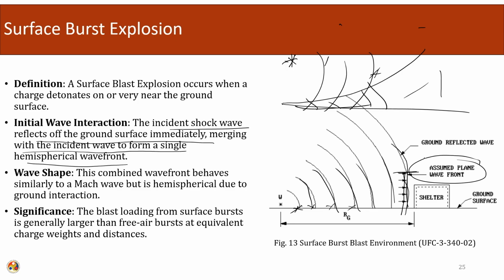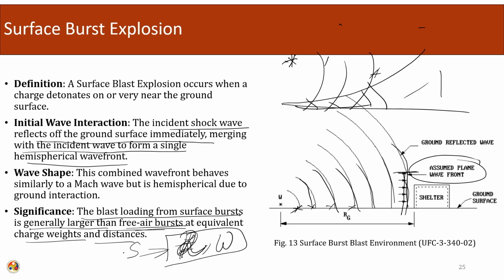Significance: the blast loading from a surface burst is generally larger than the free air burst at equivalent charge weights and distances. So, if we keep the parameters, equivalent charge weight W and the standoff distance R, the same, in this case the surface burst will have a more significant effect than the free air burst.